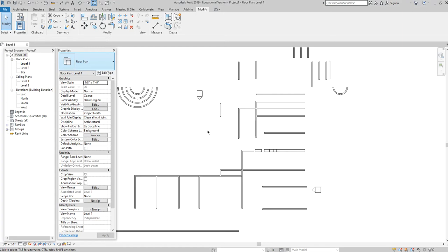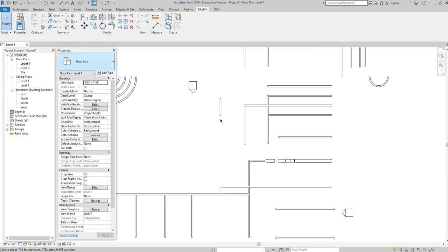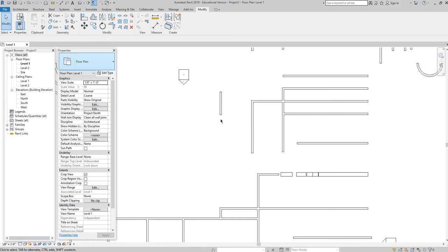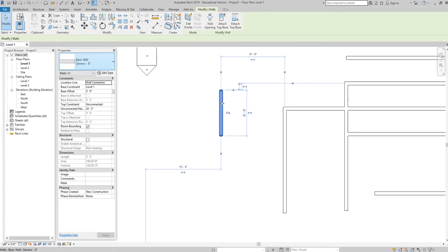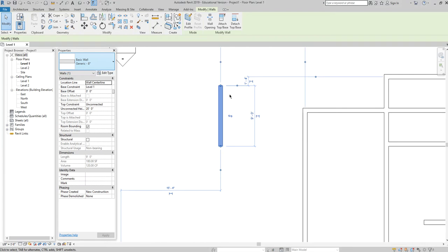The final modification command we're going to talk about today is going to be pin, all right? And those of you that use AutoCAD, pin is very much like using the lock, so locking a layer, essentially. It will take an object and permanently keep its place, which means that if I pin this object and try to move it, delete it, or alter it, Revit won't allow me to do it. It holds its place, its location, its length, and all of its settings, okay?